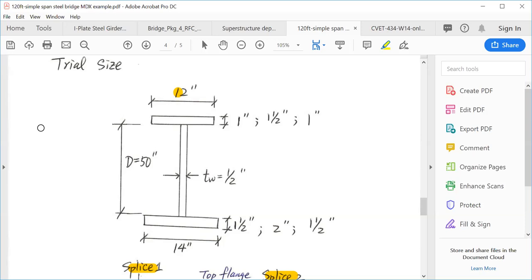If the performance ratio is greater than 1, it means the design strength doesn't meet the requirement, and you have to increase the shear strength or bending strength. For shear strength, you need to increase the thickness of the web, and for bending strength, you need to increase the size. Usually we try the thickness first, increase the thickness of the flange first, and then we can increase the width as well in order to make the flange bigger to meet the bending requirement.